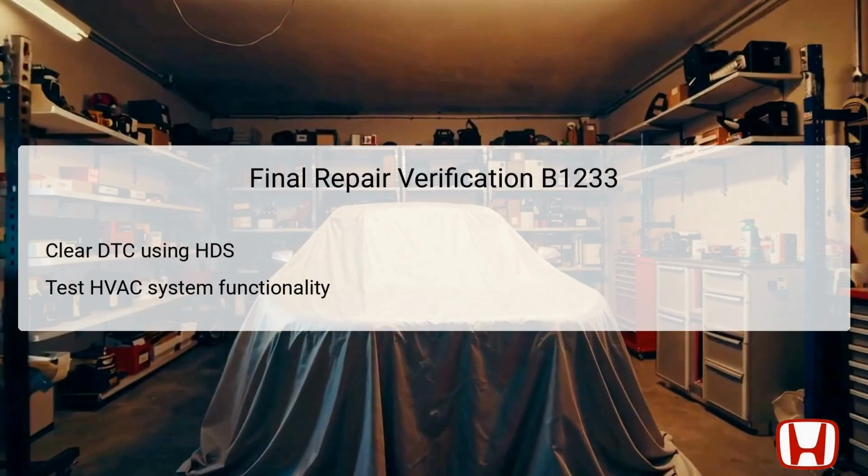After executing troubleshooting and any required repairs, it is crucial to perform a final verification to ensure that the DTC B1233 has been resolved. Use the Honda Diagnostic System, HDS, to clear the stored DTC. Following this, test the HVAC system for functional performance to see that it's operating according to driver settings.